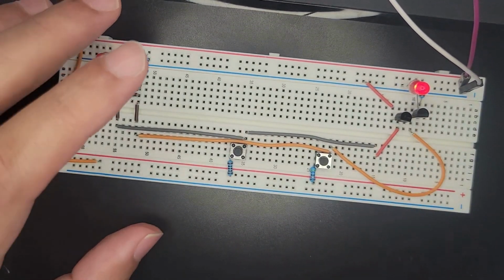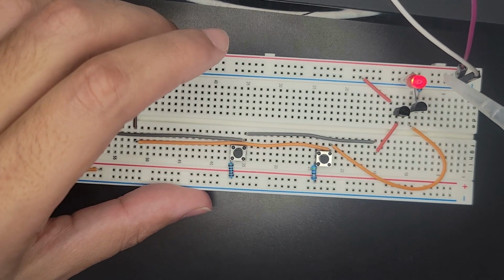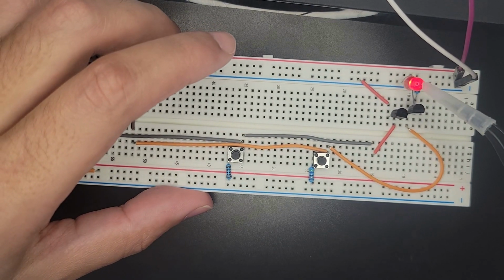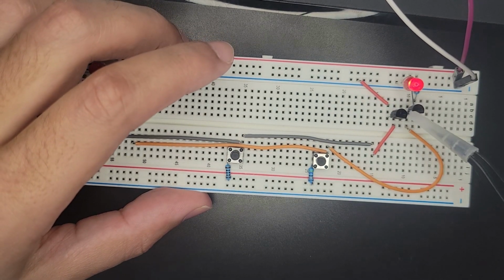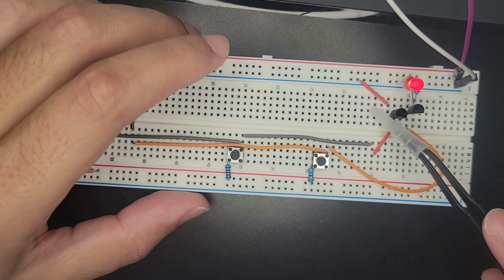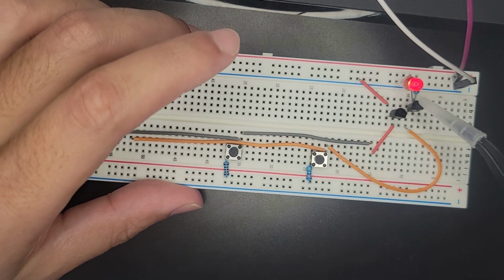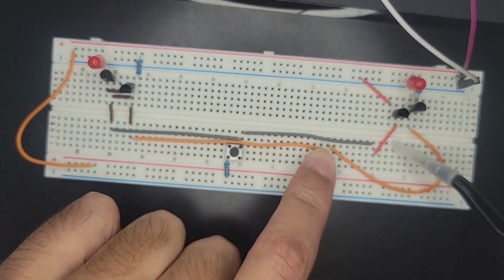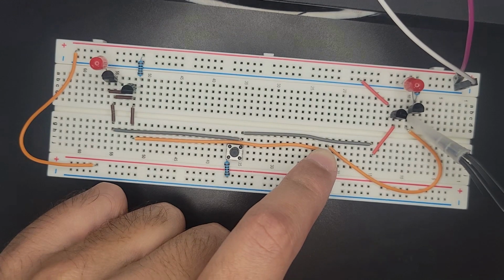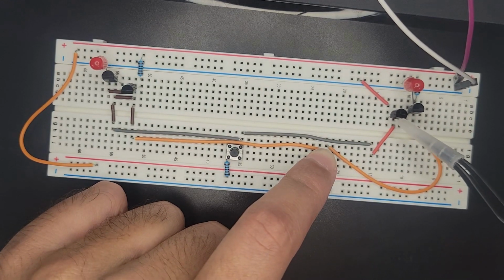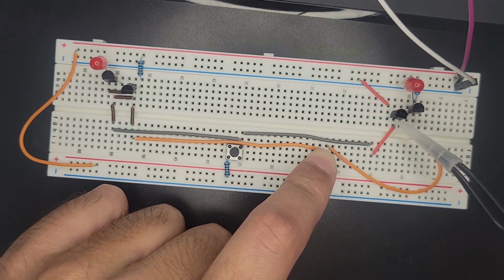And this guy becomes an OR gate, which is so weird because the only way for the power to skip the LED is to go through here. And both of these bases need to be activated for that to work. So for one button to be pressed, for A to have the base energized, it should get stuck in the collector of B and not be able to go out the emitter. So I don't know what's happening.